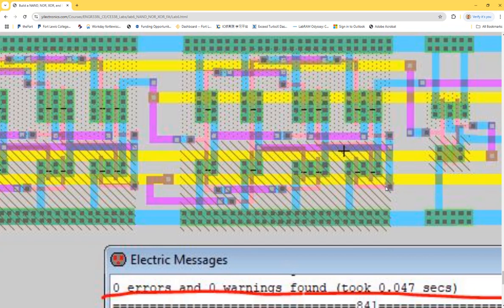To reduce the resistance. You just cannot directly use poly as a trace, as a wire. It has high resistance, right? If you use it as a wire all over the places, it's dropping voltages. Resistance dropping voltages. Because of Ohm's law, right? You get current running through the resistor, it drops some sort of resistance voltage, which is bad. So even for this very short distance, I believe it's just a few hundred nanometers, I still don't want to just use poly. I convert it to metal first and then come back down to the poly layer.